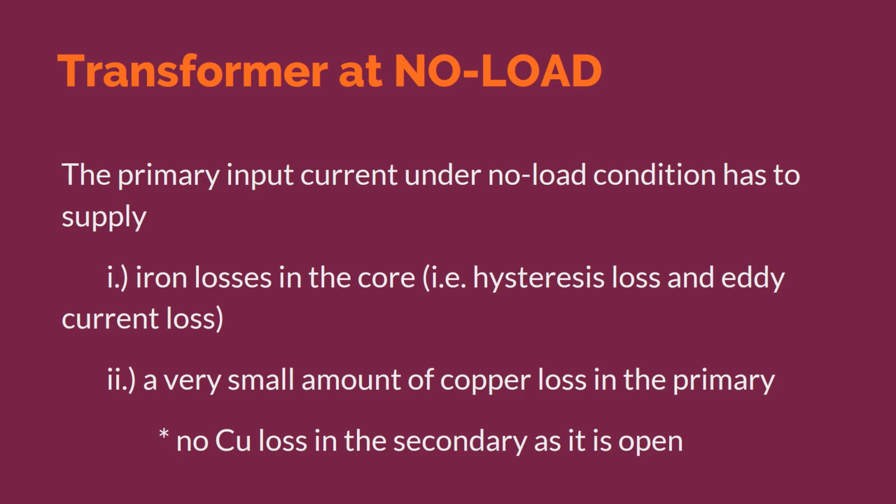When we have an ideal transformer, meaning we have no core losses and copper losses. However, practical conditions require that certain modifications be made in the foregoing theory. When an actual transformer is put on load, there is an iron loss in the core and copper loss in the windings, and these losses are not entirely negligible.